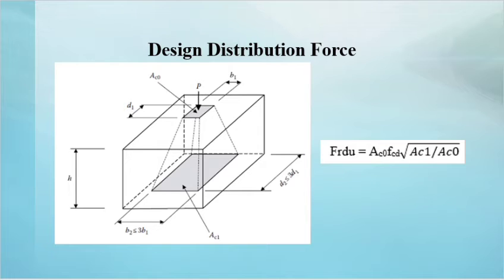In this method, if we have more than one anchorage or steel plate, we must consider that the areas of Ac1 do not overlap with each other. For example, one steel plate can produce one Ac1, and two plates produce two Ac1, which do not overlap with each other.